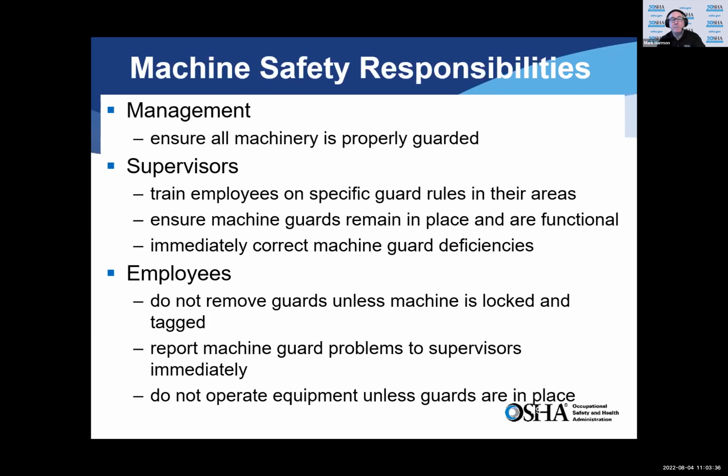Back to the slide. Employees should be trained so as to not remove guards unless the machine is locked and tagged, right? Lockout tagout is a big issue with machines. When you're operating it in a functional operational mode, you're making parts, you're making widgets, the guard should be working in place. But if the machine is in need of service, you may have to take those guards off. Make sure that the person that's doing that is authorized, right? They know how to do it.